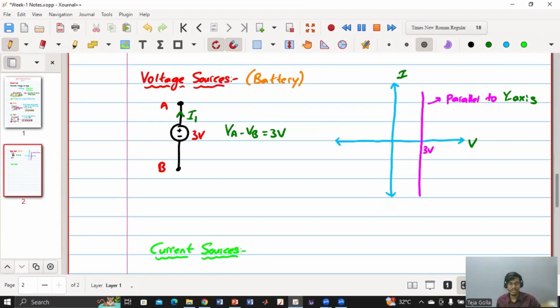We do not actually directly get a current source like we get the voltage source. A current source has to be made using some circuit elements. So any large inductor can be considered as a current source. And if you have studied electronic circuits, then you might also know current mirrors. In those current mirrors, they use MOSFETs like a current source. So it is another application of MOSFET.